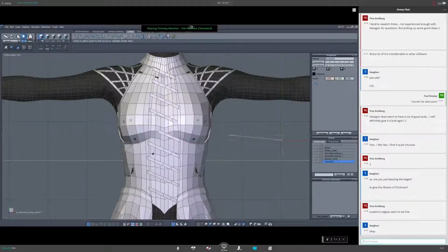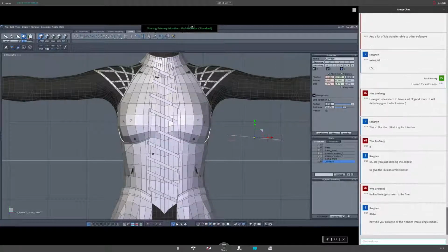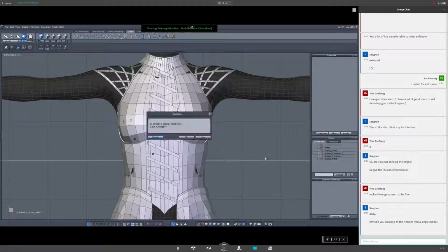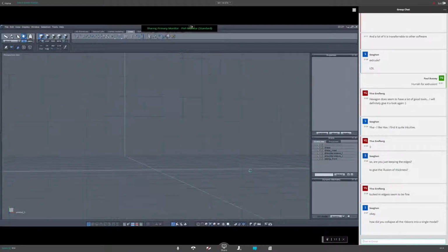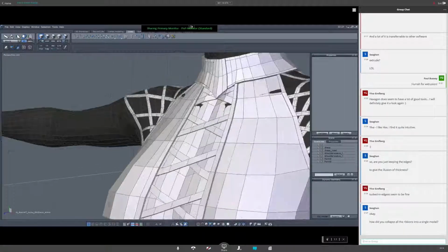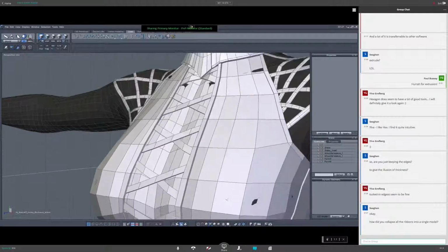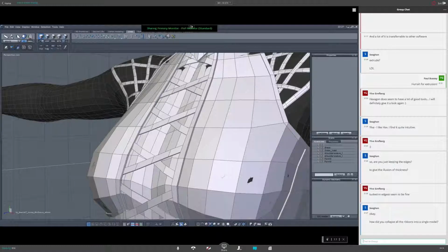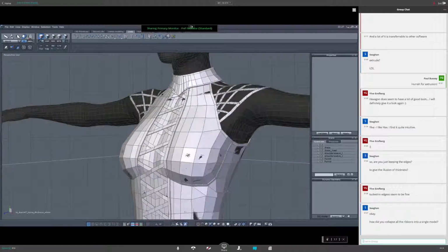You create one, position this, extrude your ribbon, add more edges with the tessellation tool, nudge it into place, and so on and so forth. You give the lacing thickness in the end, you mirror them, and then you nudge them so you have this one goes over, one goes under pattern. That's it.